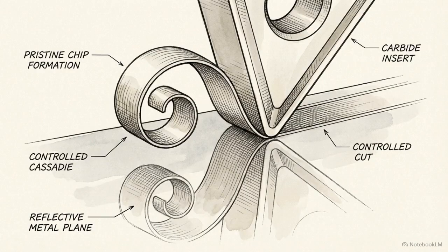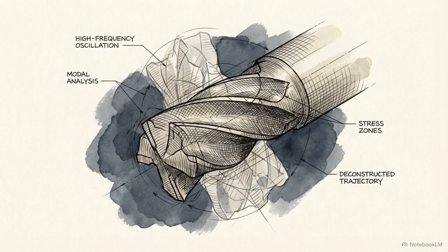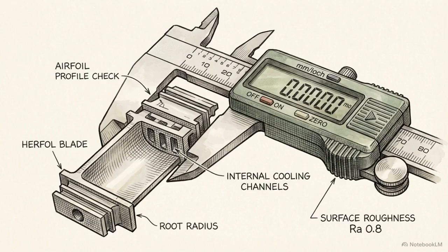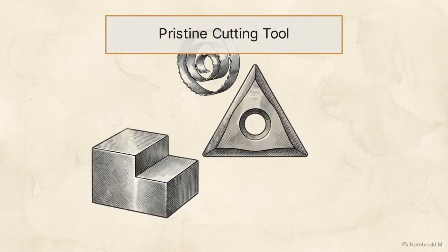During the initial break-in phase, a pristine cutting edge reaches a steady state, separating material smoothly and efficiently. But this microscopic junction is immediately subjected to extreme variables: immense shear forces, severe extrusive friction, and a rapid, intense spike in localized heat. This thermodynamic battleground is where macroscopic part quality, both the final surface topology and the dimensional accuracy, is ultimately decided. This schematic shows a 2D cross-section of a pristine cutting tool engaged with a workpiece.